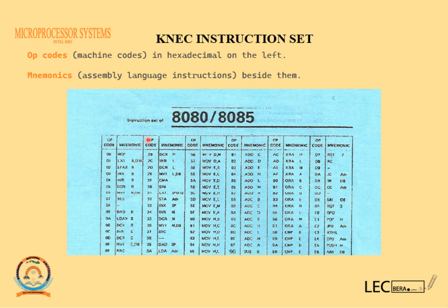The opcode is the instruction itself, the operand is the data which the instruction is working on. Now, as you know, opcodes are machine codes, and they are normally written in hexadecimal. These are found on the left side of the instruction codes which are given in 8085.